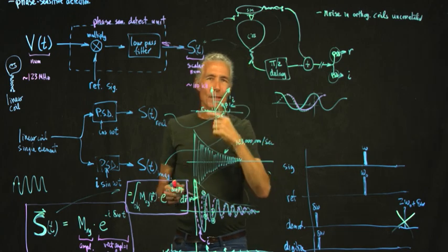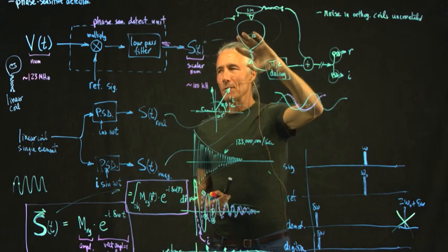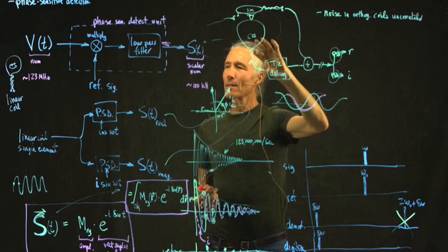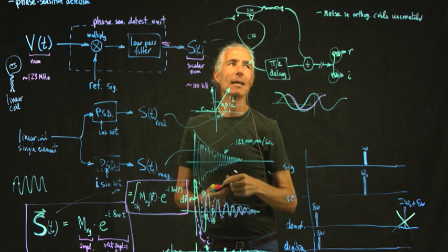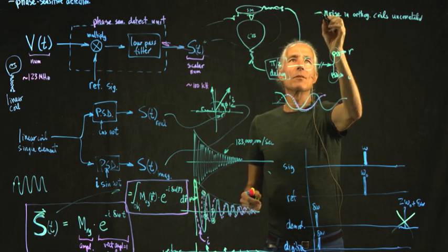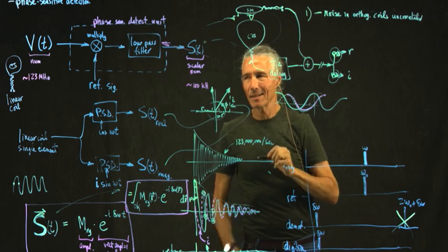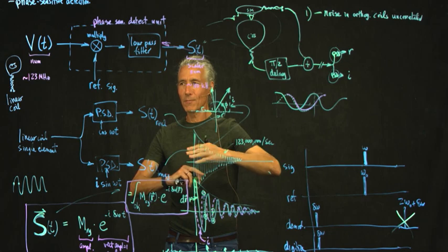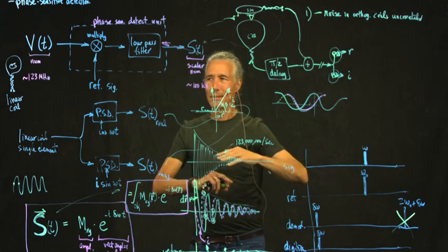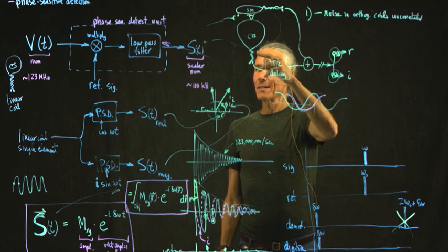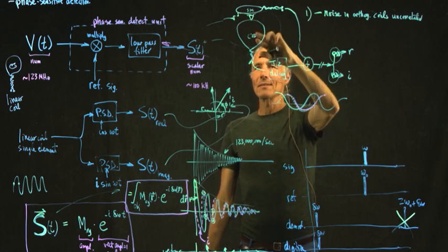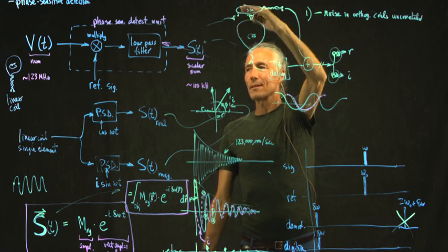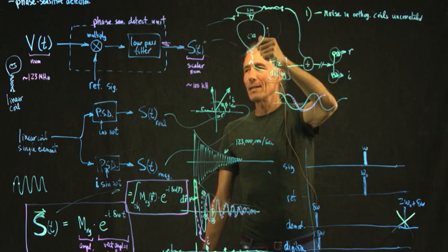Now, I might have mentioned earlier that one of the ways of making better signal to noise is to use a smaller coil. That's a different concept. One idea is that if you have two coils at right angles to each other, they're uncorrelated, but there's only two available right angles to work with. So there's no three-part quadrature coil. The quadrature coils just have two phases. There's only two possible things that are perpendicular to each other in 2D.